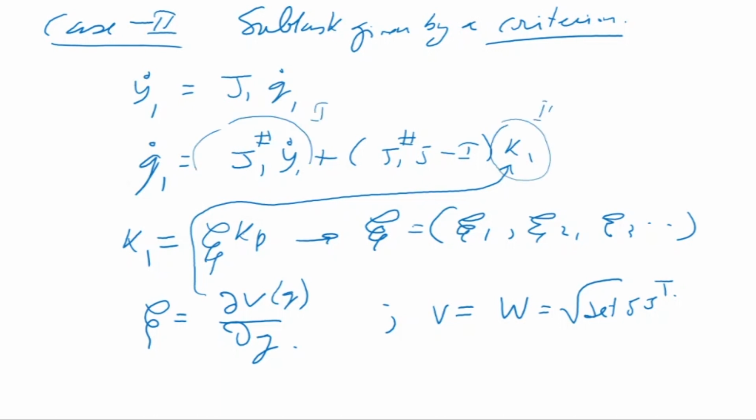So your second task is optimizing manipulation ability, or following the gradient of manipulation ability, and this is solved as an instantaneous optimization problem. This is one way by which we can optimize the manipulation ability when we are moving. If you are in a particular location, you find the Jacobian, find the manipulation ability, the determinant of J J transpose, and take the derivative, which will become dw by dq. And then follow the gradient.